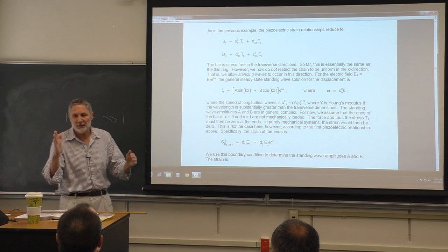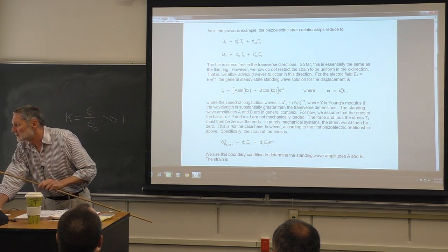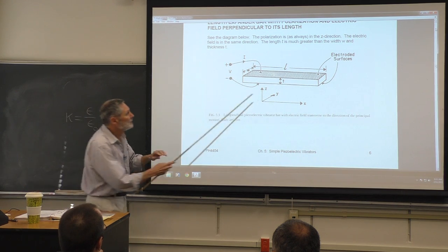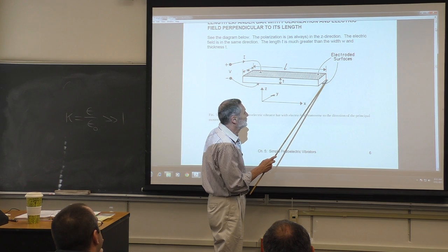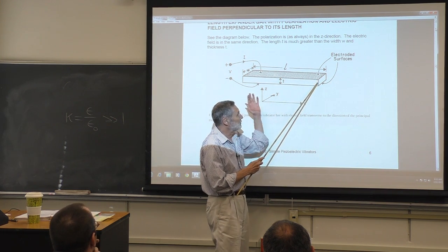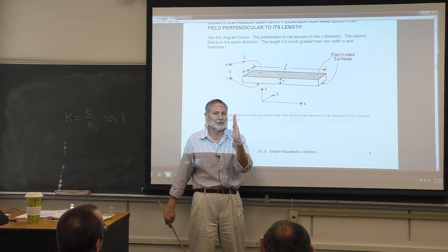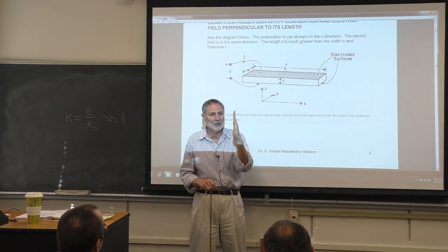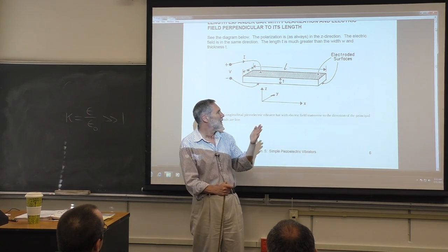So what does that mean? If I look at the end here, there's no load. There's no stress out here. If you focus your attention on the face here, it has no mass. There can be no net force on this boundary, on this area right here.